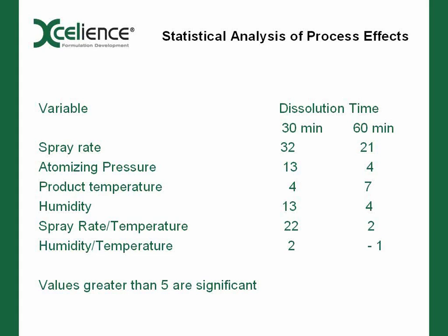Part of it depends on the process. If you're doing a direct blend and tableting, that's much easier to scale up than if you're doing a wet granulation. Part of that depends on whether you have the same equipment train going from beginning to end. Meaning, if you're doing a wet granulation on a small scale, does it operate the same as what you would see on a larger scale? And that's probably where I see more problems than anything else: just trying to keep consistency of both your raw materials and equipment, and having enough API available to be able to do the work appropriately.